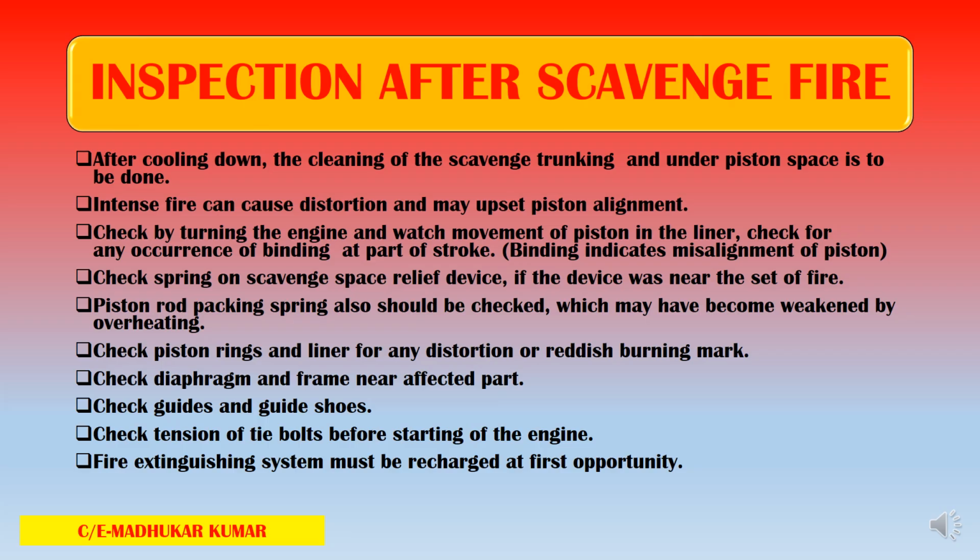Check the spring on the scavenge space relief device if the device was near the seat of the fire. So the scavenge space relief device also has to be inspected. The piston rod backing spring also has to be checked, which may have become weakened by the overheating, and if it is, then it should be replaced.